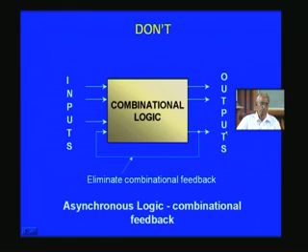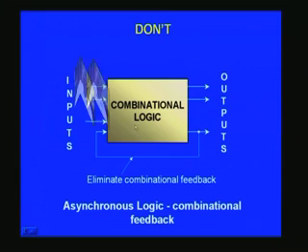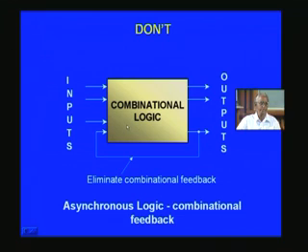When you use the synthesis tool, this is not permitted. It will give a warning or error message as such, and perhaps you can veto that and go along, but ultimately you will end up messing the whole design as such, for the simple reason that your design will not work on the ASIC or FPGA that you have ultimately done, and that is the reason why we should stick to these RTL coding guidelines as such, without which you won't get a working chip as such.